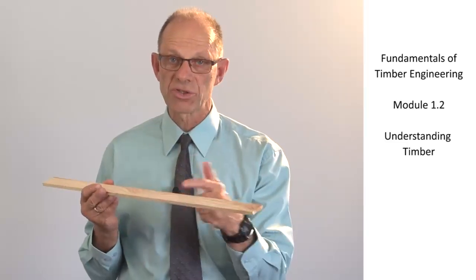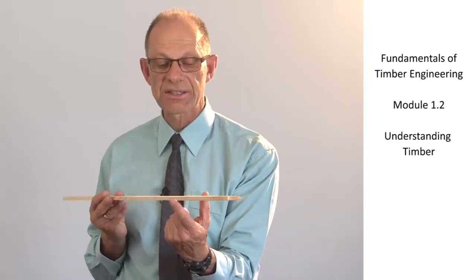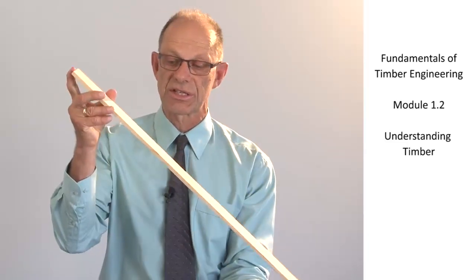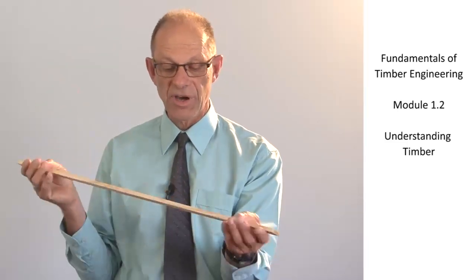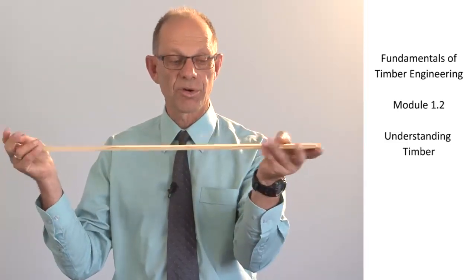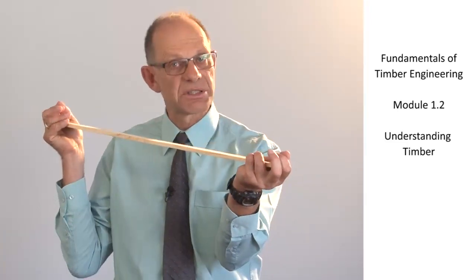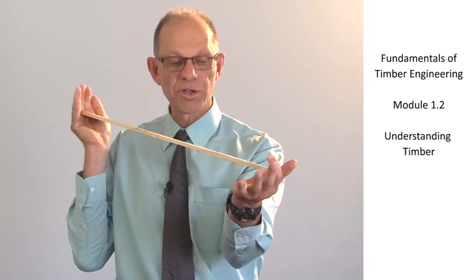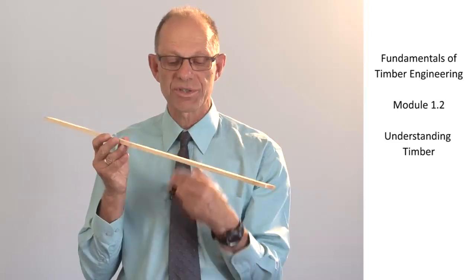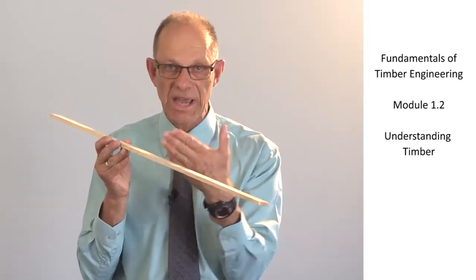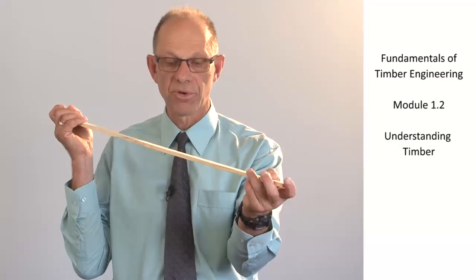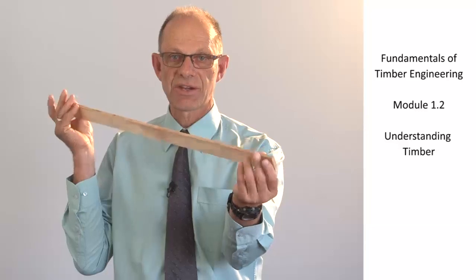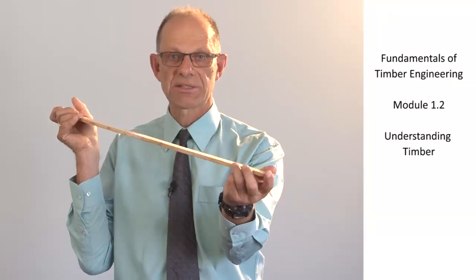Moisture does move into and out of the timber in service. It does affect its size perpendicular to the grain, but it doesn't change its length appreciably at all. And finally, in a bending application or a compression application, the timber does respond to moisture and duration of load by creeping. All of these are things that happen because timber is a natural product. And if we understand the way the timber performs, we're going to be able to design it to get best possible structural use out of this really beautiful and amazing structural product.